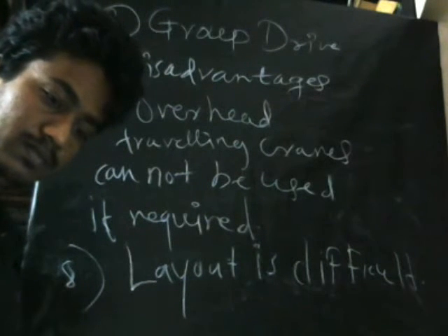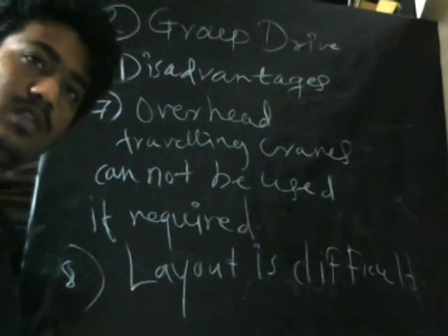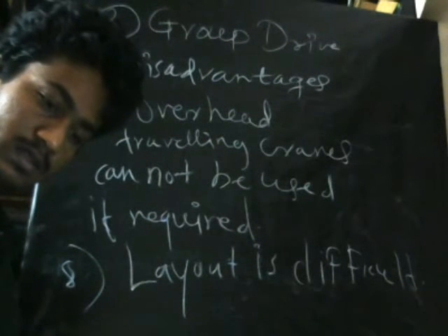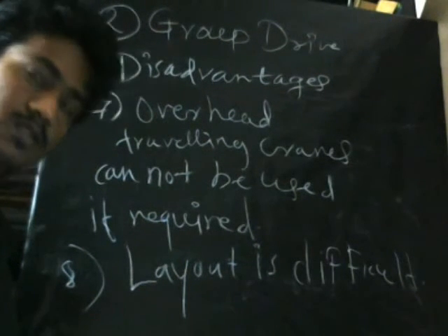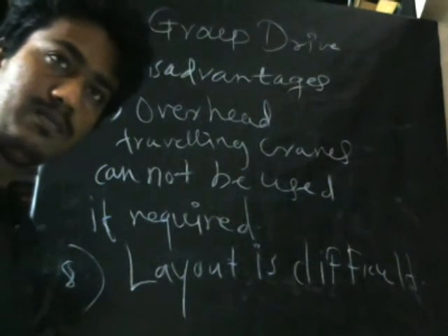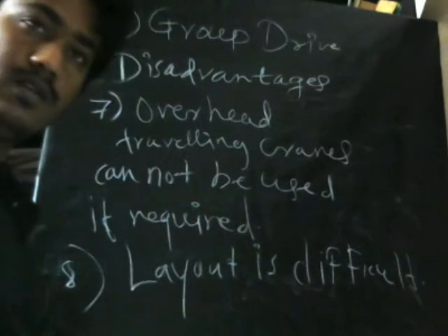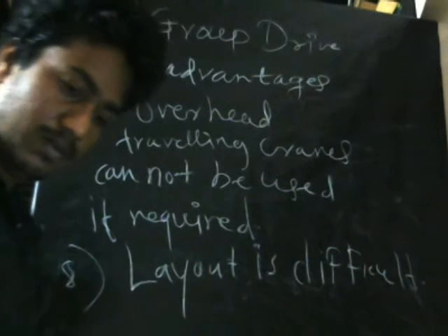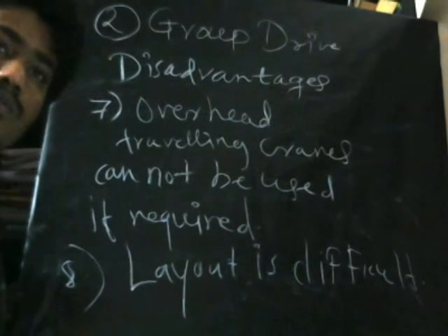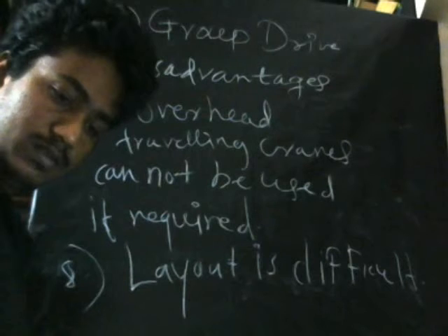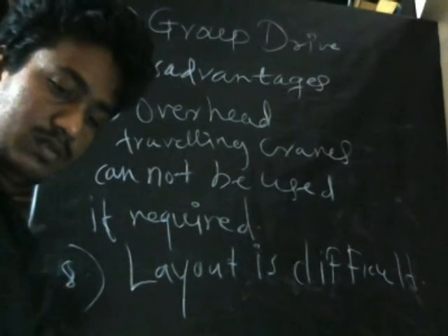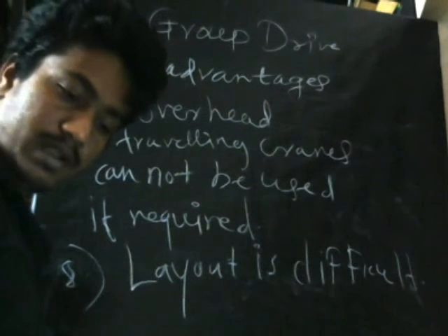Now, when a machine is driven by a single pulley, we get power directly from the pulley on one shaft, that is the main shaft. Transmission of the motion and power from the main shaft to the counter shaft is done by belt drive.